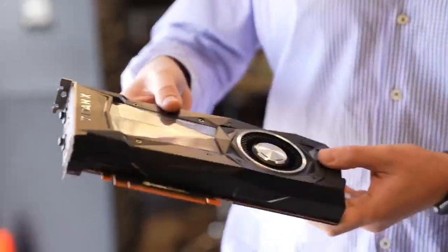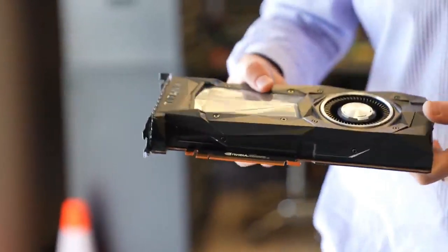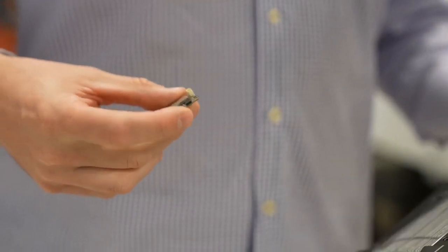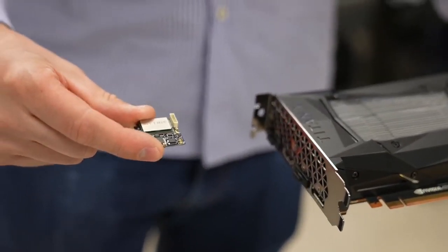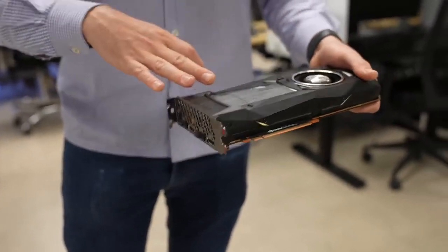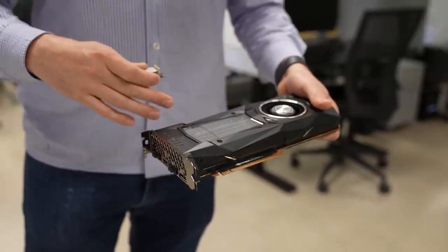How does it compare to a digital chip? The newer digital systems can do anywhere from 25 to 100 trillion operations per second, but they are big $1,000 systems that are spitting out 50 to 100 watts of power. Obviously, this isn't like an apples to apples comparison, right? I mean, training those algorithms, you need big hardware like this. You can just do all sorts of stuff on the GPU, but if you specifically are doing AI workloads and you want to deploy them, you could use this instead.